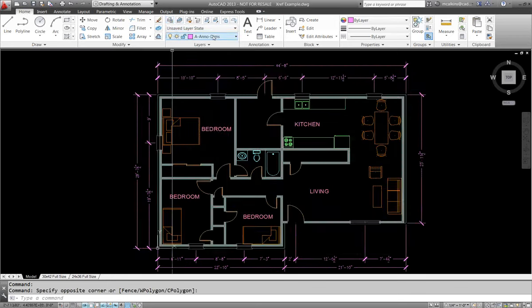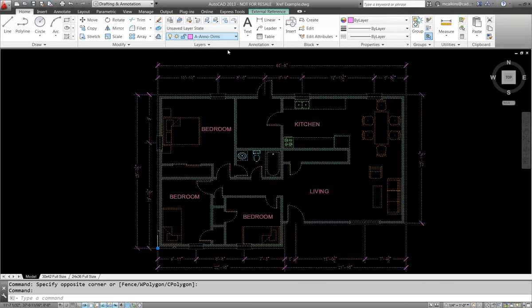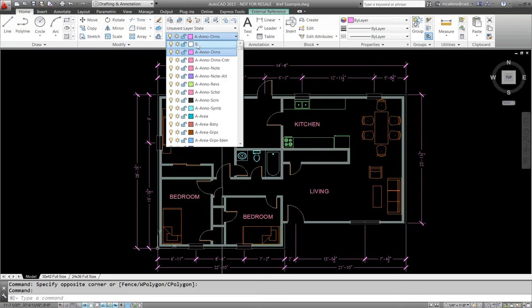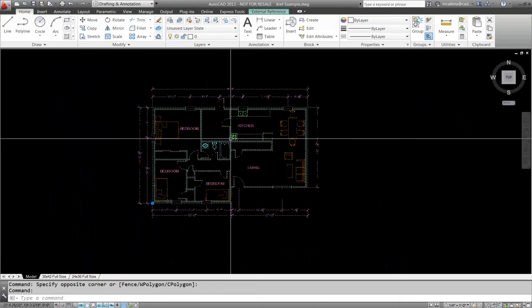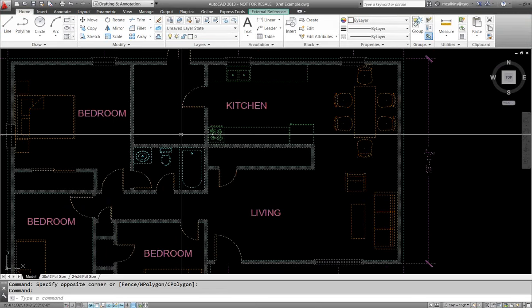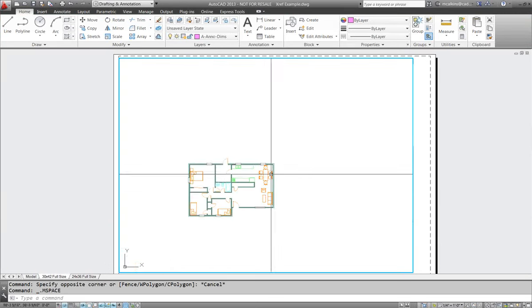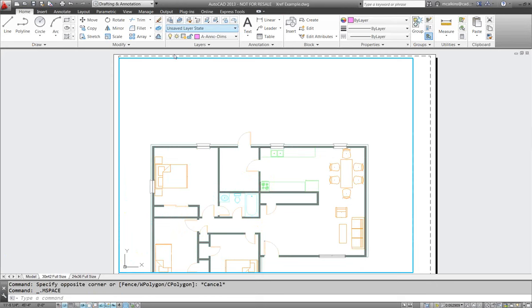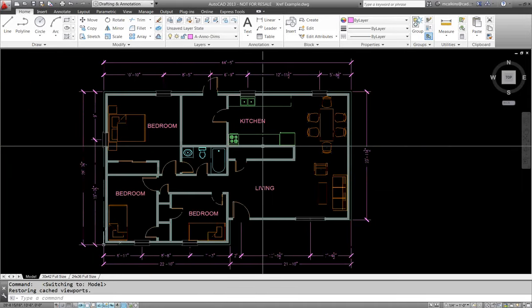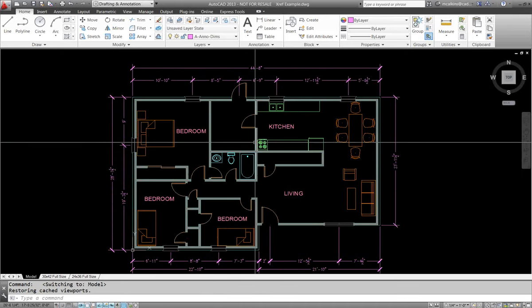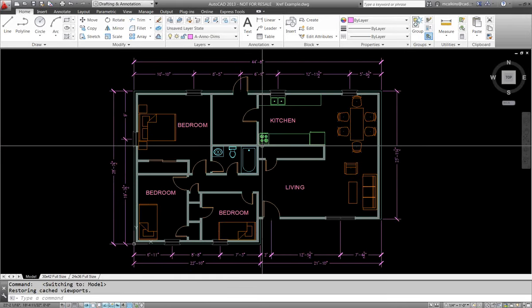Here we go, just a second, select it, place the whole thing on layer 0, or place it onto a new layer called XREFs, or main level XREF, whatever you want to call it, so that you can then go through a viewport, and here in the Layer Properties Manager, or you can use your freeze, depending on your settings, you can just freeze it, and it will do a VP freeze on the layer that contains the XREF. Again, there's several settings that will play into the behavior there, but yeah, that's one option. Put it on its own layer.